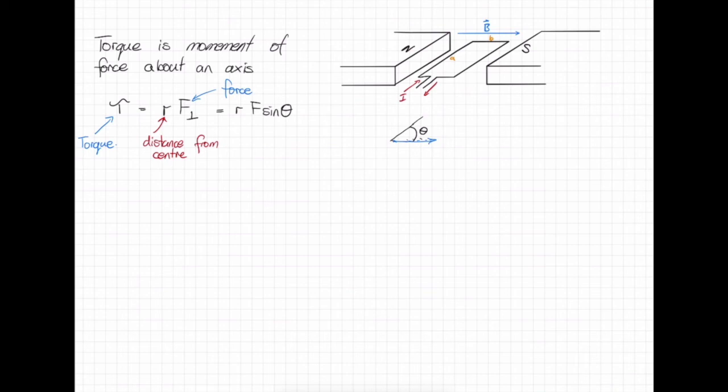When we're talking about the torque inside of a DC motor, we know that that is going to be dependent on the current. We also know that we have two wires here and here that are perpendicular to the magnetic field. Our force that we're going to be able to get from this is going to be 2I, the current flowing through, B, the magnetic field that goes past, A, because that is the length of our wire, and we have two of them, and sine theta. Because sine theta is telling us at what angle that coil is sitting at is depending on how much force we're getting. So let's look at the maximum force.